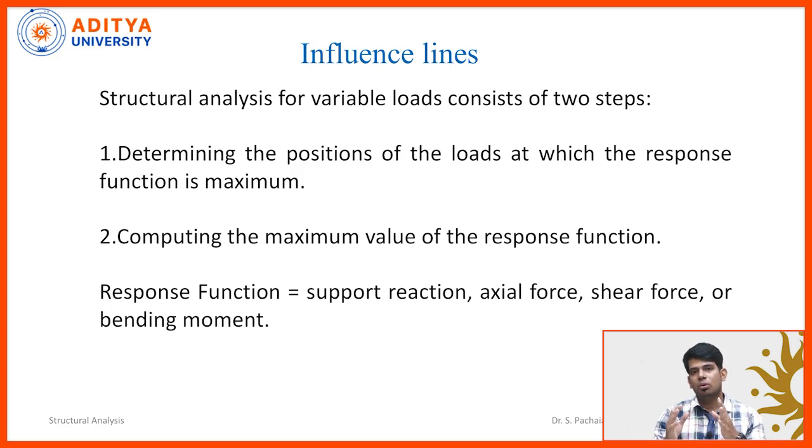If I keep the load in which location, will I get the maximum bending moment and deflection? First of all, we need to find the location where the maximum shear force, bending moment or deflection is happening. Accordingly, I will design the structure. So determining the position of the loads at which the response function is maximum is the first thing.